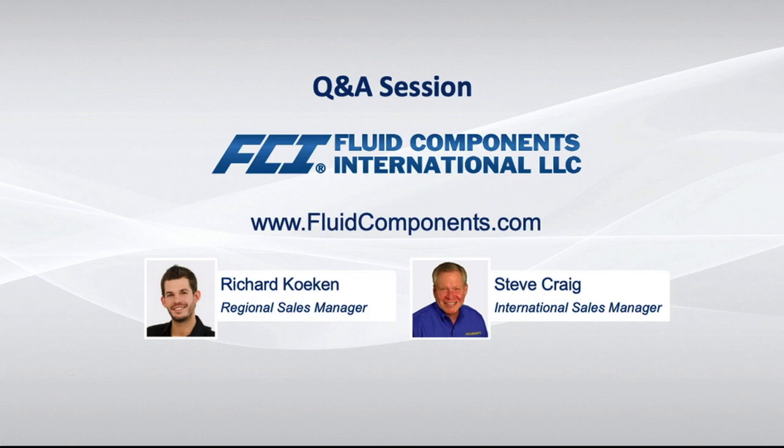Gentlemen, our first question for today: will each measuring point have its own analog output, or will these be connected to a remote transmitter, which will provide one output? Hi, Katie. I'll take this one. Yes, each measuring point will be connected to one remote transmitter, and the remote transmitter will average the input from those measuring points and provide an average mass flow measurement through the analog output or Modbus RS-485 or Foundation Fieldbus or Profibus communication.